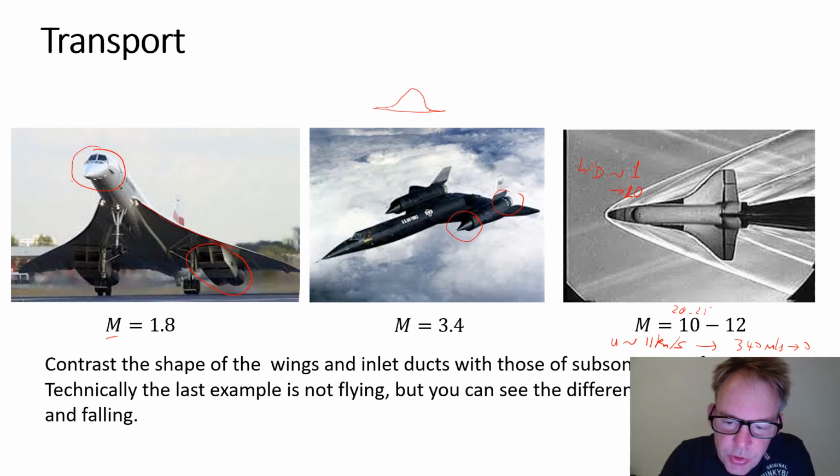And so there are some very interesting features of this shape. Particularly the fact that there's a lot of heat dissipation due to the presence of these quite severe bow shocks on the front. Now that's a feature in all of these, that the dissipation that occurs on the surface, on the attached boundary layers, causes a significant amount of heating. So compressible fluid mechanics, on the practical side, is both a fluid mechanical problem, a thermodynamic problem, and also one associated with material selection.